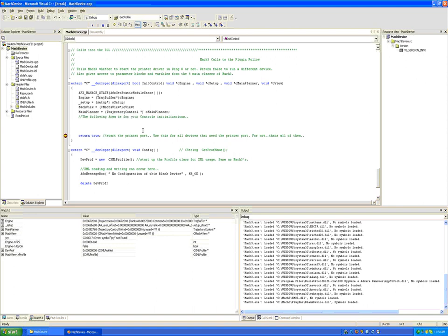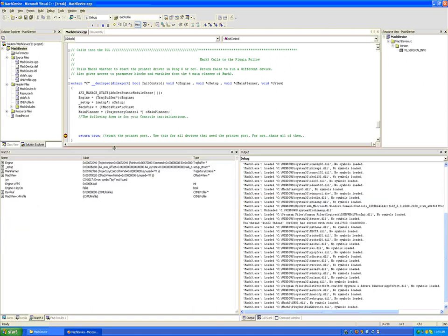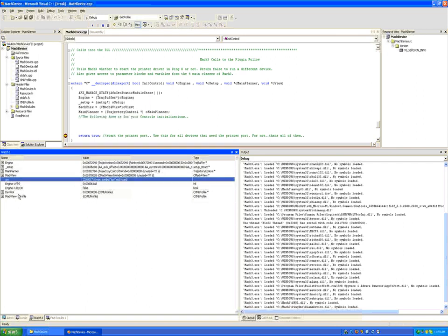This is in order to conform to certain internal intricacies of Mach3 and to maintain a synchronicity with the XML profile file. But all we've done in this particular initialization is set pointers to our engine, setup, Mach view, and Mach planner and main planner variables. If we look down here at our watch function, let's slide this up so you can see a bit more. And I realize the video here may be very bad, so you're going to want to try this yourself.